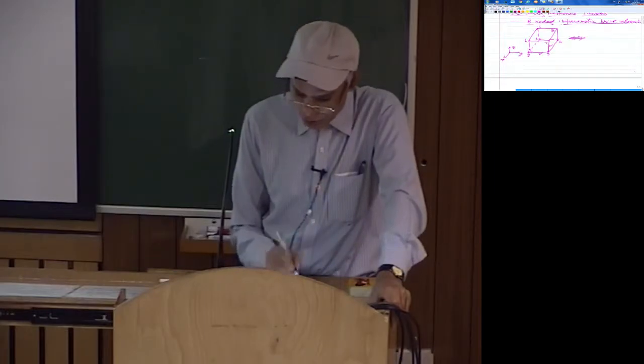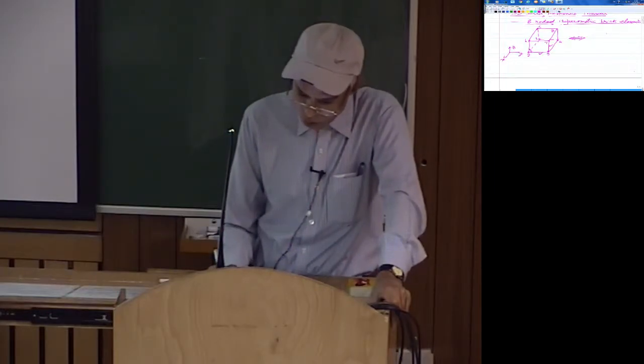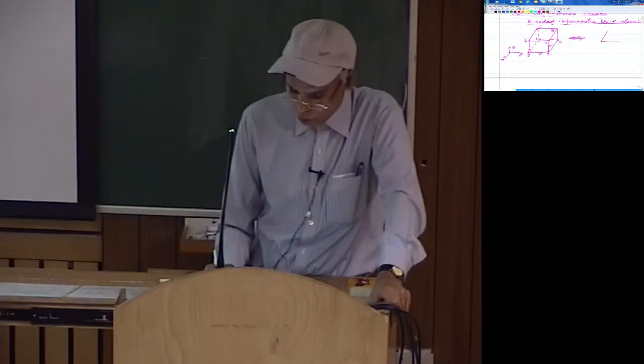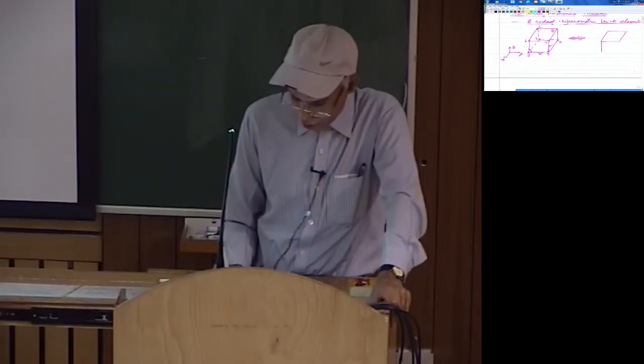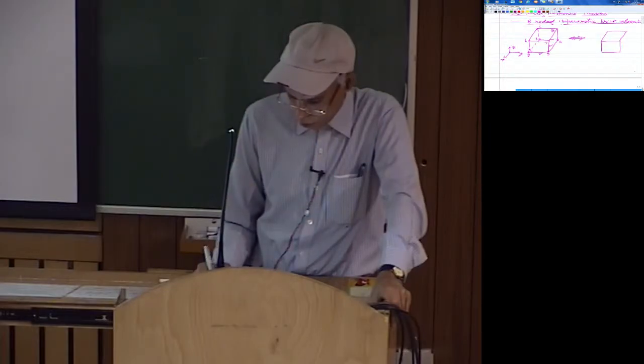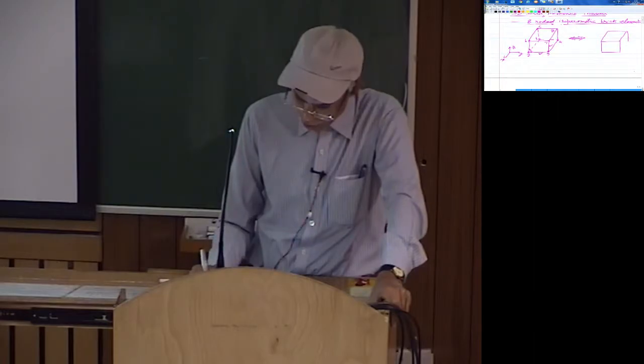So this is the element in the physical coordinate space. Of course, in the natural coordinate space, this is always going to be a cuboid of side 2. It is always going to be a cuboid, whereas here it can be any parallelopiped.